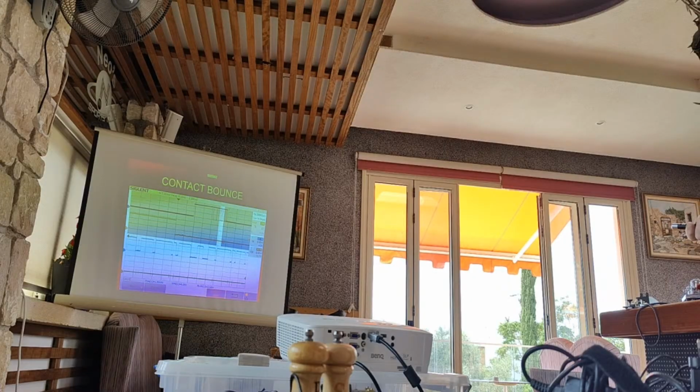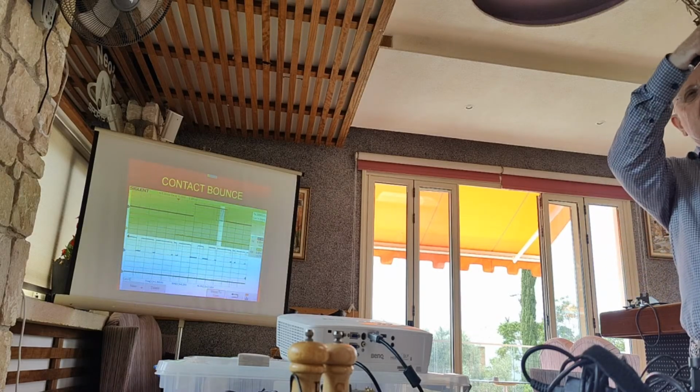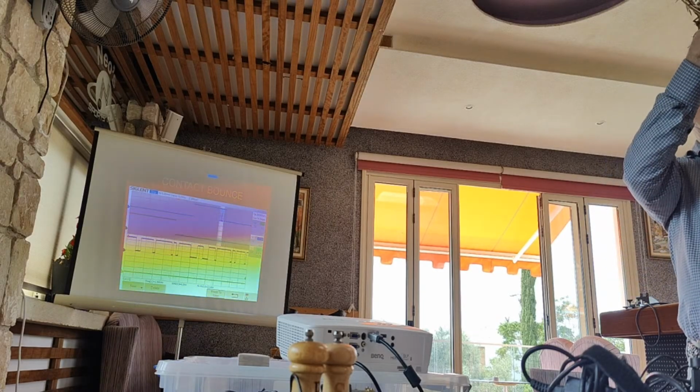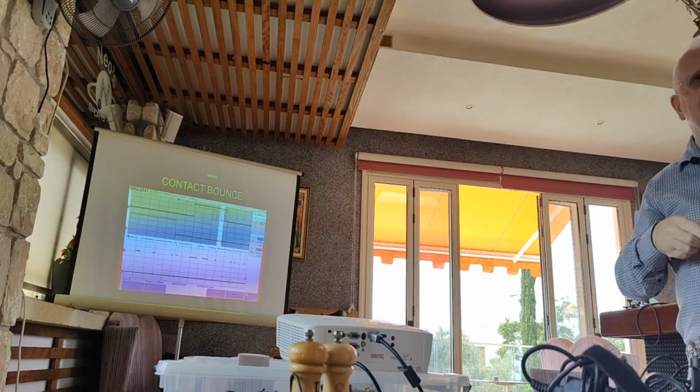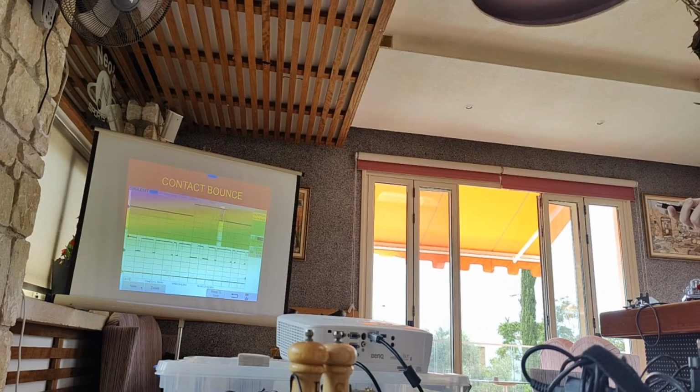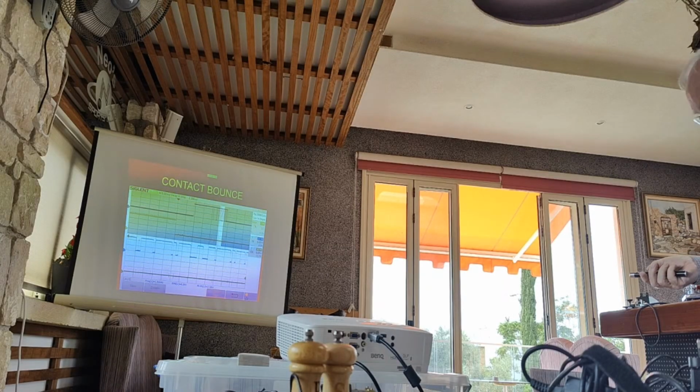This is actually a power relay. And what I did was, it's a changeover relay. So you have a normally closed contact, a normally open contact, wire the two together and connect it to ground, and pull the armature up to plus 12 volts with a resistor. Connect the scope to the armature and to ground, and here we energize the relay, and note it takes nearly 10 milliseconds before anything happens.